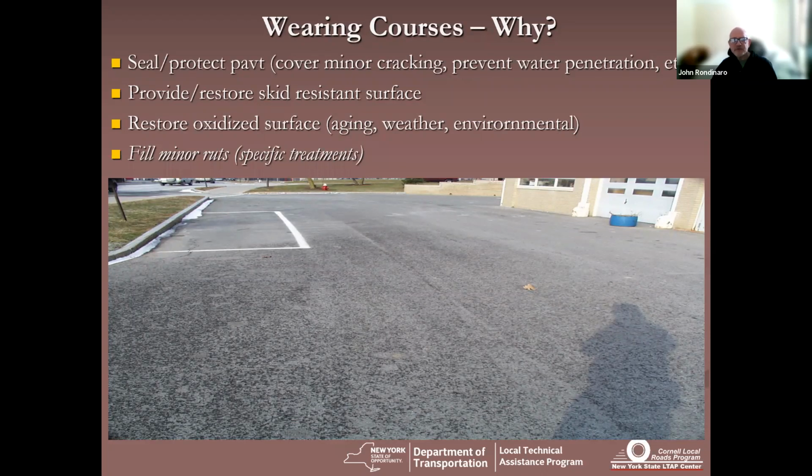A point about this picture right here: when your pavement looks like this after a recent precipitation event, and that pavement's starting to dry out and you get this salt and pepper mottled look, that tells you it is the perfect time to consider some sort of wearing course or surface treatment, because water is just starting to be able to penetrate into that surface, and you want to get it sealed back up so that water beads off and rolls right off of it.